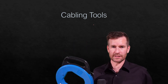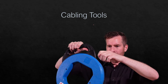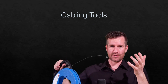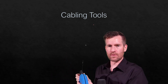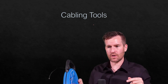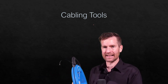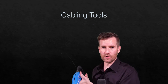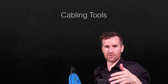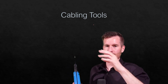Another thing for cabling as well is you may see some fish tape. The fish tape is a stiff cable, and you take it out and you can fish this cable through walls and through ceilings. This is 100 feet, so you'd take the route that you want the cable to go, and you'd fish it through all of that. Then I've got some electrician's tape here, and I'd tape the cable to the end of that, and then I would pull that cable back through, maybe through ceilings or through walls, or to get it through tight places that you can't really get to and physically put the cable in there. You'd be able to do it with this.